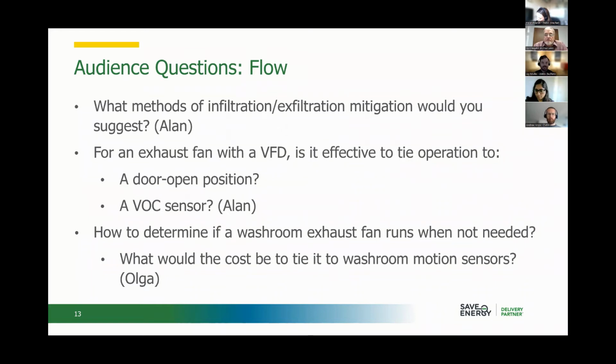And to take a very short rabbit trail here, one of the issues with bag houses that the EPA south of the border here has done is in steel plants, they want to see all the bag houses in the future be on the clean side of the fans and be under negative pressure. And the reason why is because they don't like them leaking, and they don't want that dust coming out into the environment. The problem with this is that once upon a time, we could see that dust coming out into the environment, whereas now when they're all under negative pressure, leakage is coming in. You've got no way of seeing that.